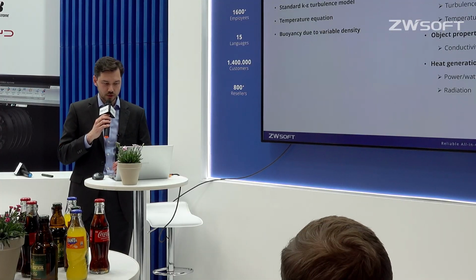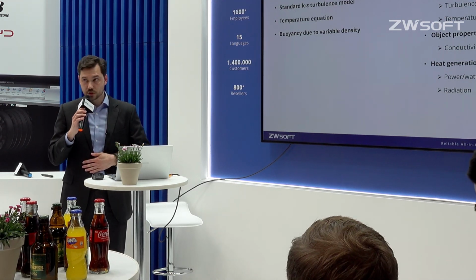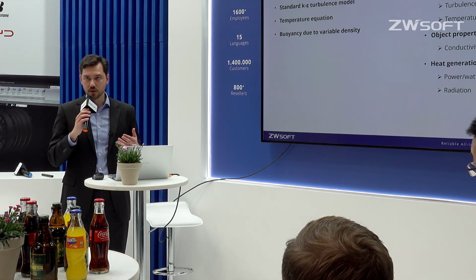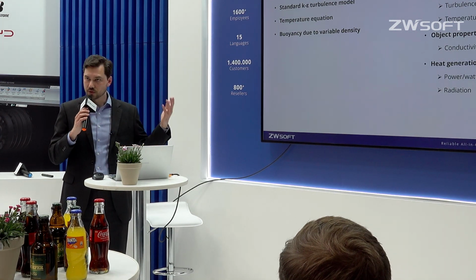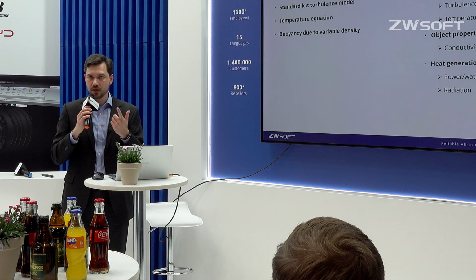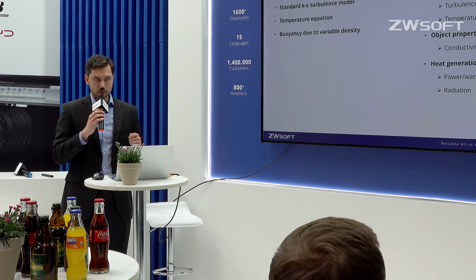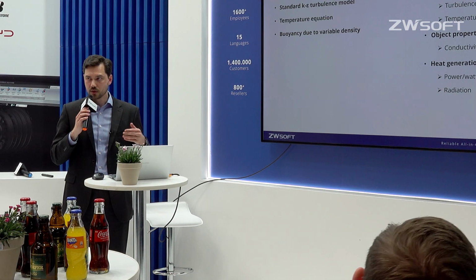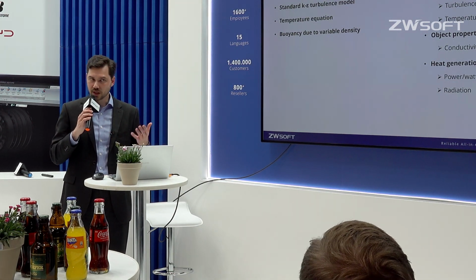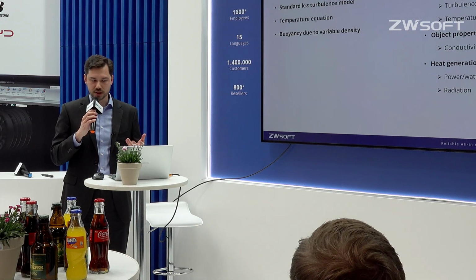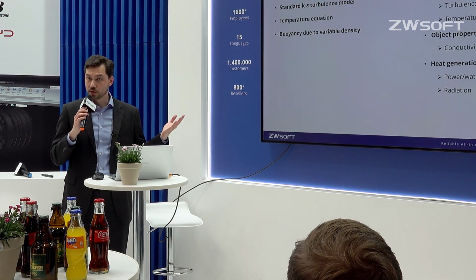We also need boundary conditions, because all of these problems where you have partial differential equations are bounded. In this case, the boundary conditions are the inlet conditions for the velocity and the heat generation from the chips. When you have a fluid flowing, there are two states in which it flows. It can flow laminar or turbulent. Well, these are the major states. In our case, we know that the flow is turbulent. So for our model, we also need to include a turbulence model. And for a turbulence model, we require boundary conditions that someone from the upstream department has to give us. So we need to be confident in what the information is that they're handing to us.